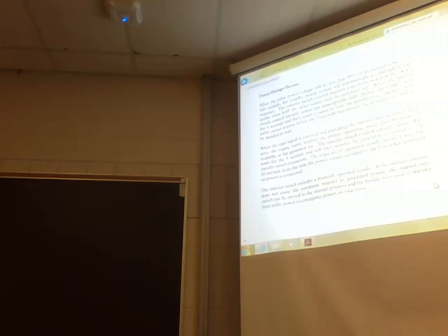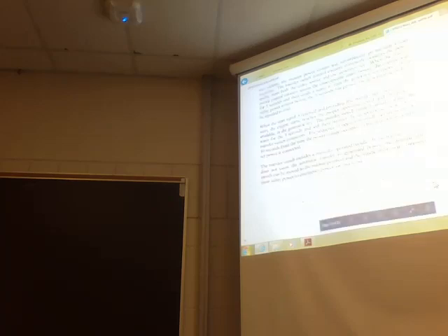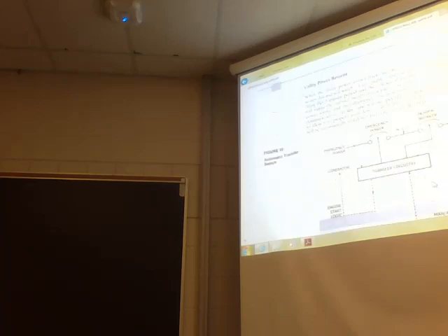When utility power comes back on, the transfer switch control circuitry senses this and will watch for acceptable voltage levels for a period of 5 minutes. After this period, if the voltage levels have been stable, the control will signal the transfer switch contactors to retransfer the load back to the utility power source and then disconnect the generator set source. At this point, the generator set is offline and will be operated automatically another 5 minutes to allow it to properly cool down. After this cool down cycle, the generator set will be automatically shut down and reset to standby mode.